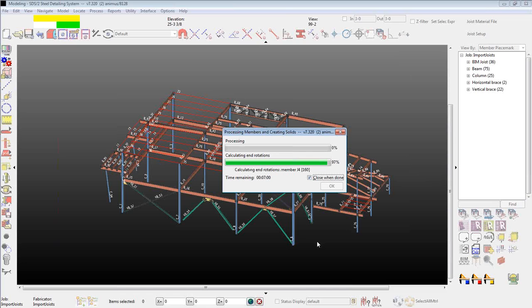The other thing to take note of here, and you're probably noticing, it definitely is not the fastest. I would say you're going to be efficient with up to 200 to 300 joists during the import. If there are more on the project, communicate with Vulcraft, see if they can export those and get it split up for you into several files if you have to.